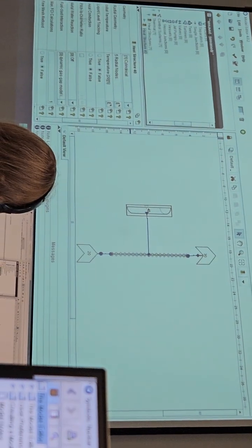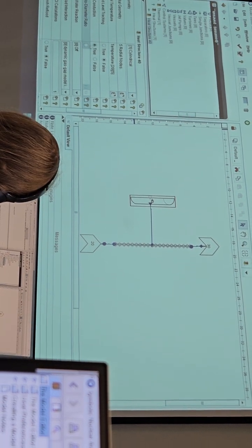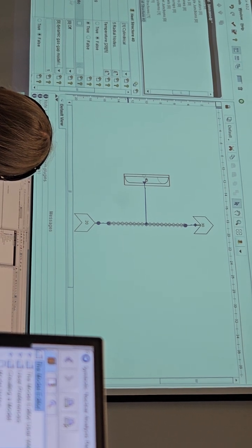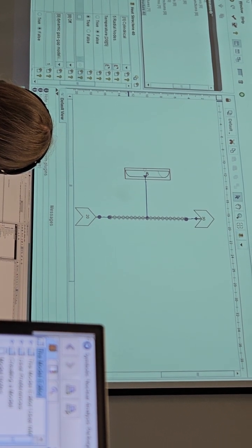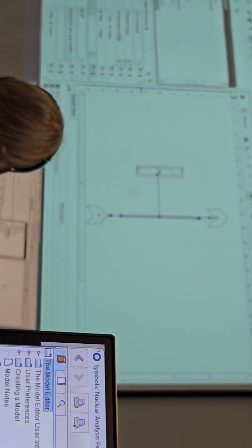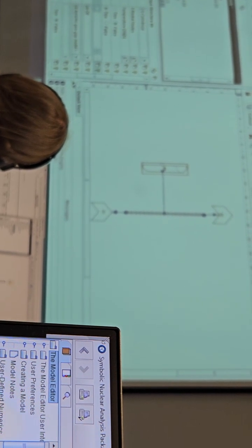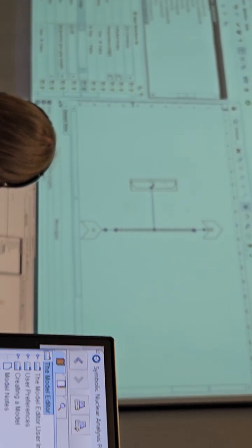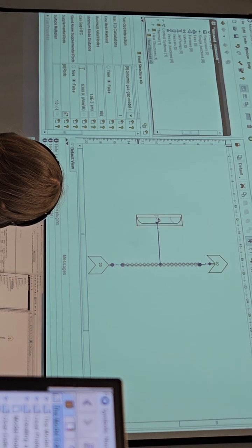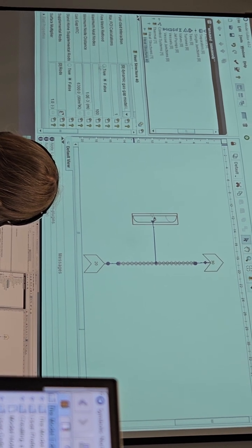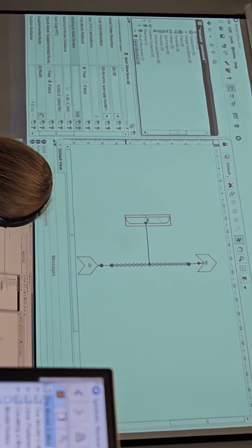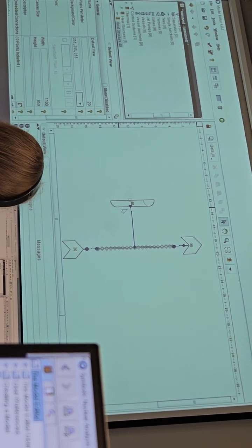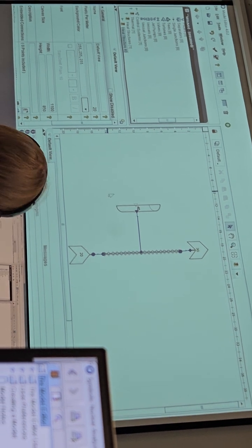We just need to define the axial conduction as true, and the fine mesh flood is true as well here. So as far as I see, everything is done for this heat structure.